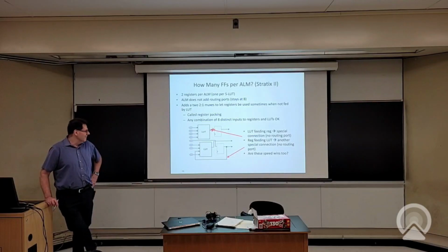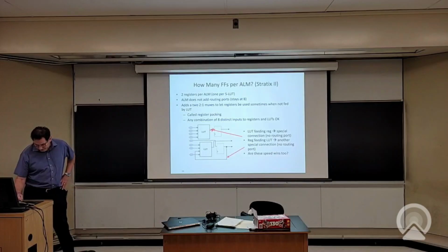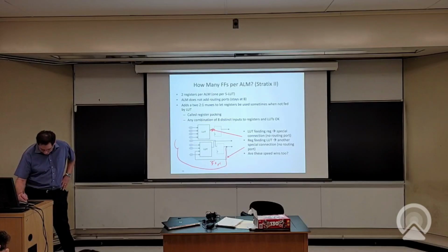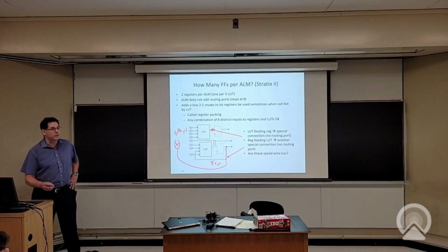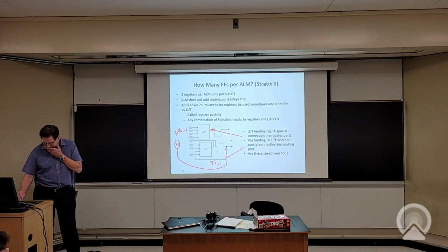No, I'm struggling because there's a feedback path, and with feedback paths, it's hard to cut them. So this is really fast. I can't remember the exact number. Say this is like 50 picoseconds, or actually it was really fast. Say it was 30 picoseconds, and going back through the local interconnect, this crossbar, was more like, in this generation, probably 300 picoseconds. So the connection itself electrically was a bunch faster. 30 is probably too little. Let's go back to 50.